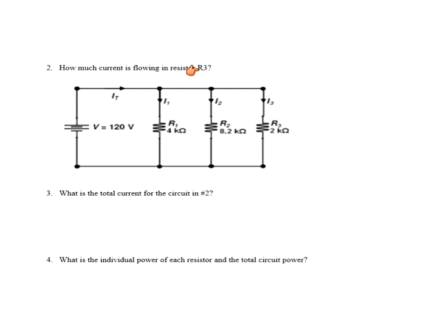Okay, well this is parallel. In the parallel circuit, what's the same? The voltage, right? So the voltage in this case is 120 volts. All right. Now, what resistor is this? Well, this is the 2K. So the current, I3, the current in resistor number 3 is equal to the voltage divided by resistor number 3, which is 2,000.